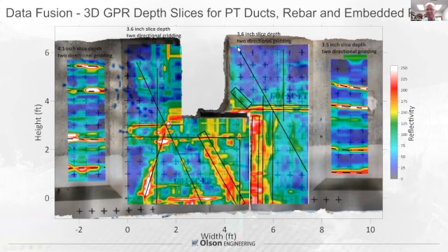So on this side of it, the top web of the other girder coming together, this is showing, again, the stirrups, some vertical steel, and 2 steel plates here and here. And then it becomes clearer at this depth slice, 3.5 inches in, that's when you see the post-tensioning ducts. So this is being sliced in this case to be behind some of the front steel. You can still see some of the front steel in these reflections at this depth of slice. And the reflection amplitude is shown on the right.